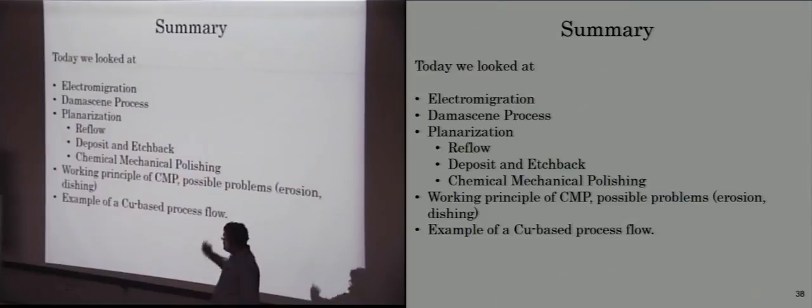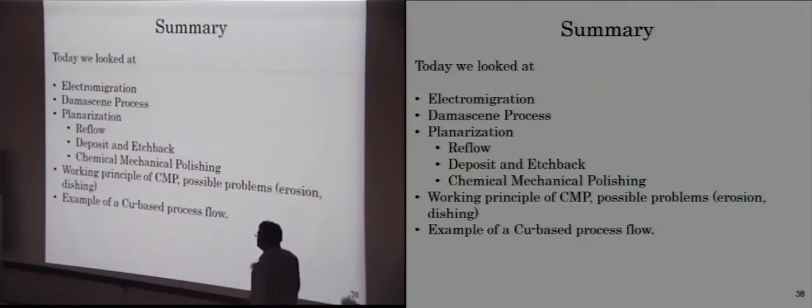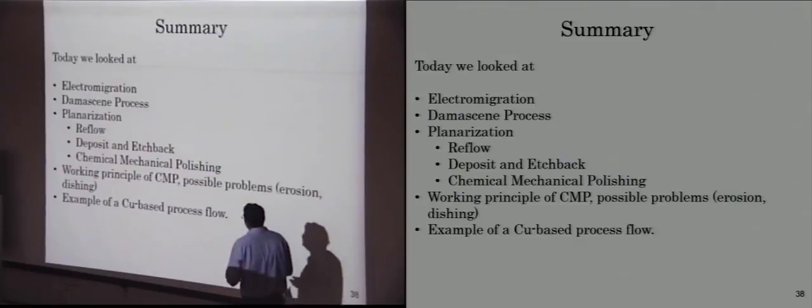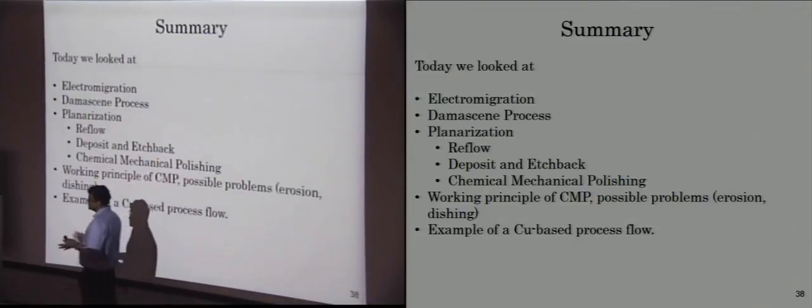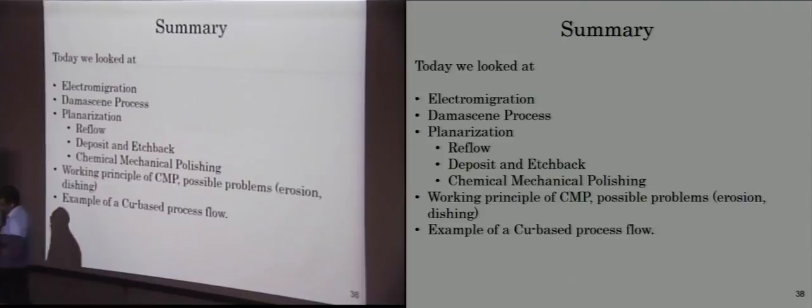In order for copper to be utilized, other factors include not only the Damascene process, you need to make sure you have diffusion barriers also, so that copper does not diffuse into the silicon. And because we are trying to fill in vias now for copper, you try to grow it through an electrodeposition process. Okay, details of the electrodeposition process will be talked about by Professor Lipowsky. All right. So this is the logic in which we form the metal lines. From aluminum we have gone to copper, and this is the way in which you build layer by layer on top of the transistors.